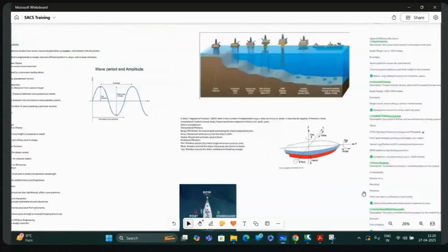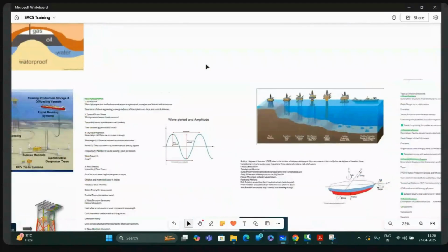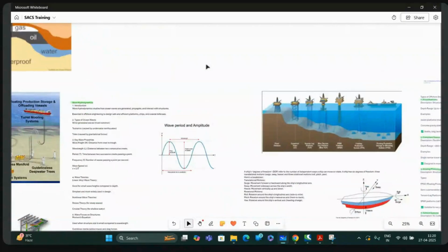Before we go into these things, what are the loads that can act on a structure? Anyone? Dead loads, imposed loads, wind loads, yeah. Seismic loads, yeah. So we will classify it into a few things. There are static loads. Dead load is the self weight plus some equipment over there. Then live load. Live load means the weight of the people and all sorts of things.